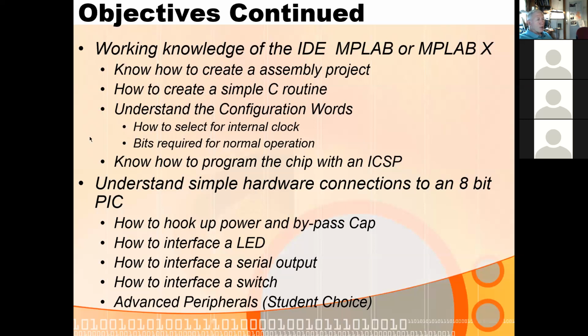On our chip, you can single step the program. You can watch in your integrated development environment each line execute. If you're in assembly, you get to see every single instruction execute as it executes. In C, if you're following in your C code, remember that each C instruction could be multiple assembly language instructions, so the correspondence is a little looser, but it'll still show you where you are in your C program.